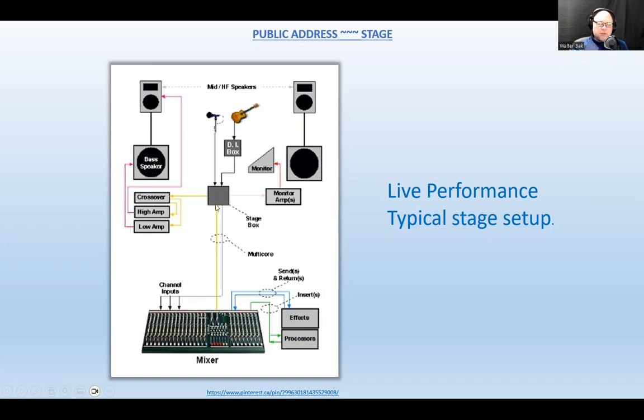If it's a digital system, then you would still have the stage box with many of the inputs, but instead of having a snake that has pretty much 3 conductors for every signal, because we're using something called a balanced signal, and we'll talk about what a balanced signal is later on, it just connects to the digital mixing board through a Cat5e cable, just like Ethernet.